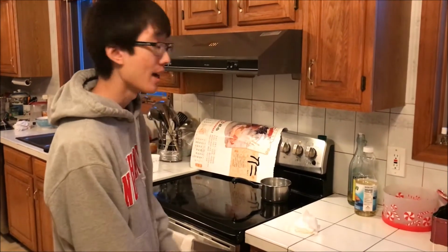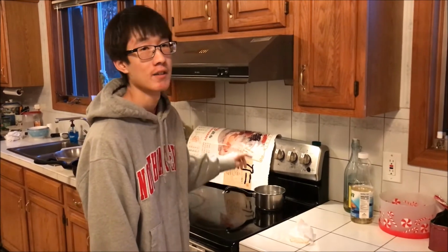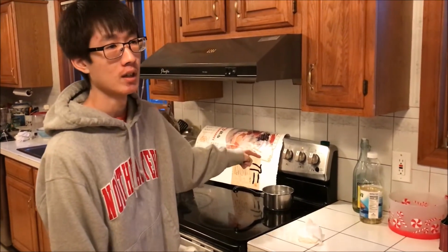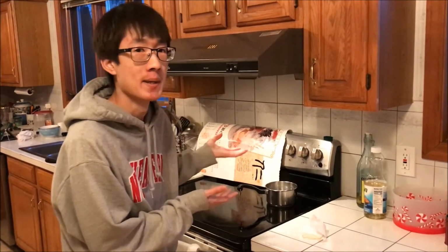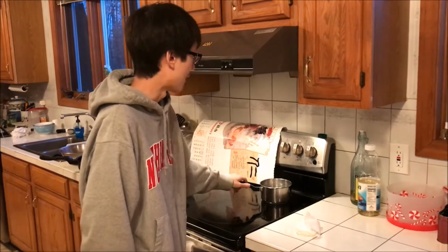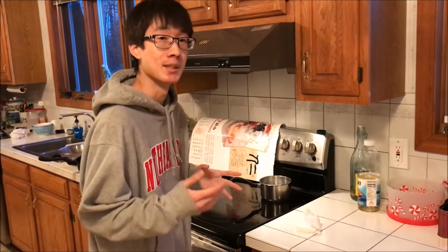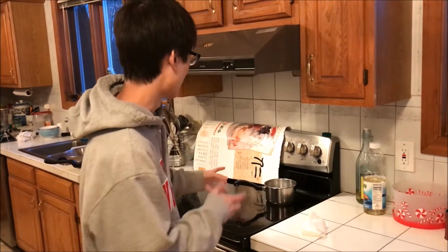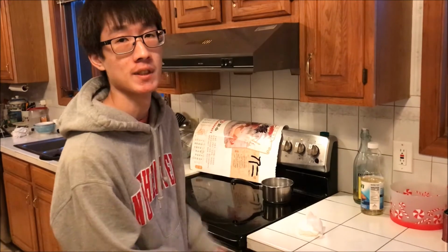So what we're looking for right now is the excess temperature of the surface of this pot from the saturation temperature of the water. Because this dial is in some strange alphabet that's not Greek and I don't understand what it says, we will have to estimate the temperature. And the way we'll do this is by judging the type of nucleate boiling that's occurring off the surface of the pot.